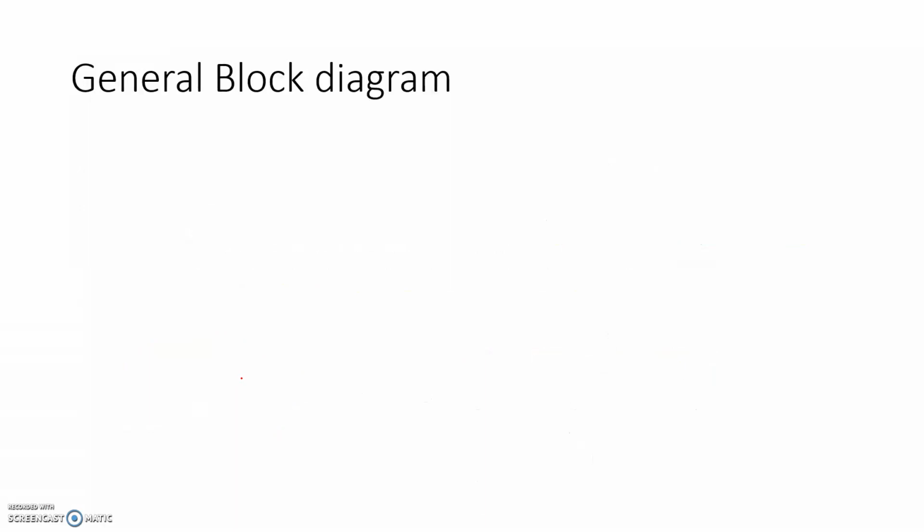Clear? This is the basic idea of combinational and sequential circuits. So what is the general block diagram of a sequential circuit? A sequential circuit is made up basically of logic gates only, like AND or NOT. You may be astonished how this is possible, because AND or NOT gates cannot store memories, right? But they can store, if we make certain arrangements. There are different standard configurations that we will follow.